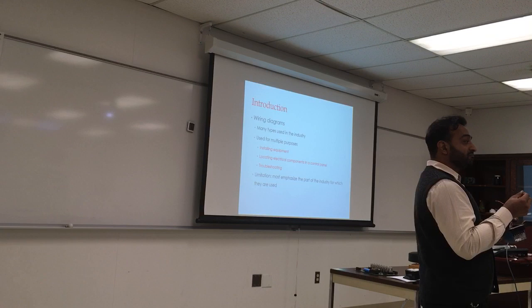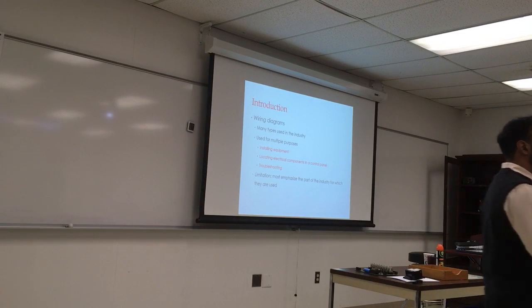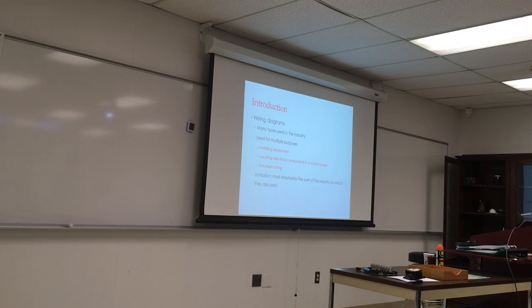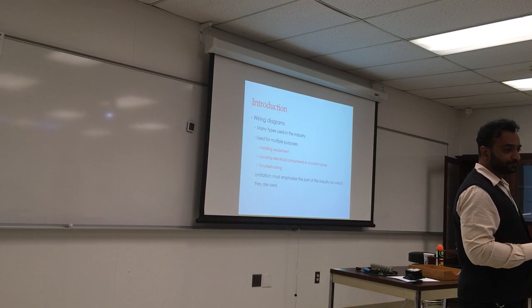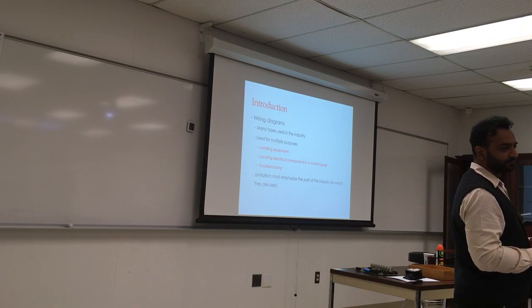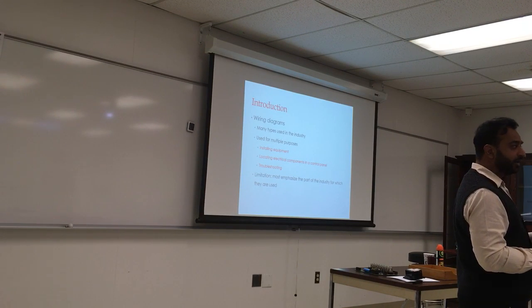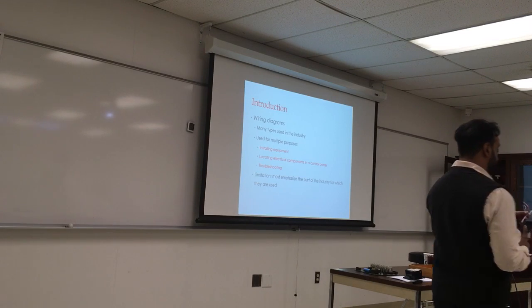Blue for oil and gas and heat usually is ignition. Orange is well known to be the motor line. The pink one is the valve for gas. If it's purple, it is the valve for oil. You'll remember these after you use them a few times. I was reading something last night where the green wire was... Yeah, either green or bare. Okay. We don't see any green wire here.